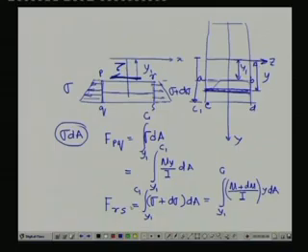So, this tau is what we call a shear stress that is created along the line of the beam. Now, you can very easily understand that if sigma on both sides were equal, that means if the beam were subjected to pure bending, no shear stress is present. But the moment there is a change in bending moment from this section to this section, there is a stress that comes into the picture, and that is what we call the shear stress.